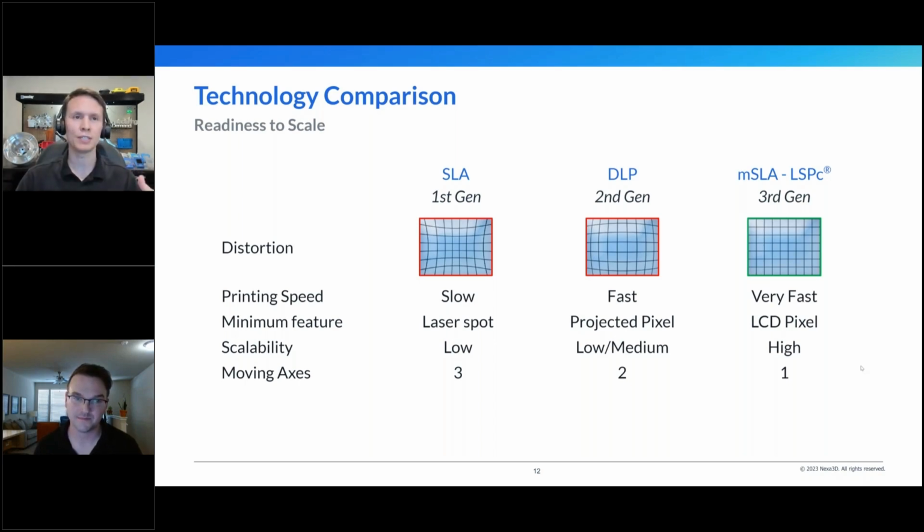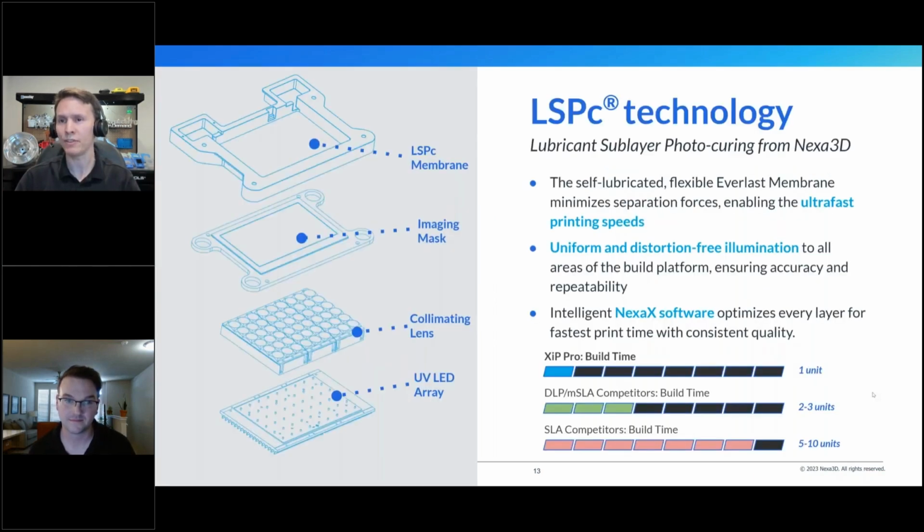This is really interesting because we have an LCD pixel system where, when it's active, it's black, and then it'll deactivate a cell and let the light shine through and create that curing effect. It does scale on XY, so you can get really big on the platforms in theory, versus multi-projector or multi-laser systems where you have weird overlap ranges, so you can have a consistent part edge to edge.